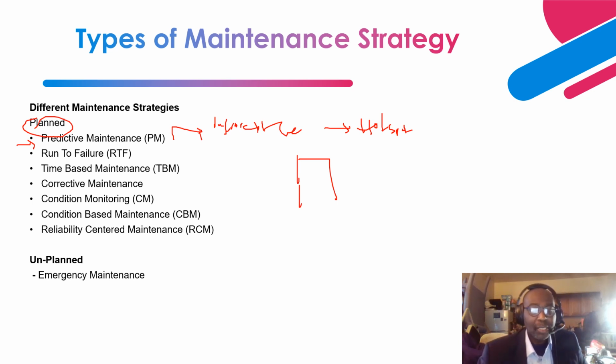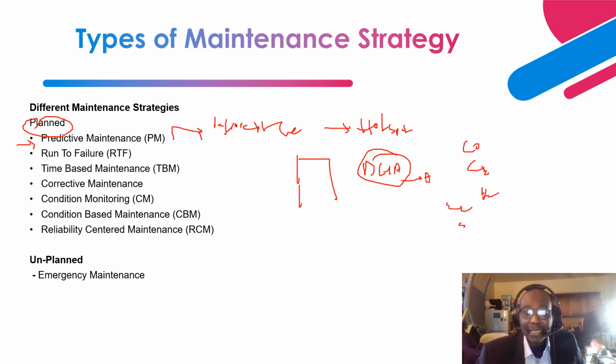Then another predictive maintenance tool that I can use for the power transformer is DGA analysis, right? Real-time DGA analysis basically samples oil, analyzes it and spits out all the gases and components: carbon dioxide, carbon monoxide, hydrogen, acetylene, ethylene, ethane, and also oil quality and moisture level. Then also for motors, you can also have vibration.